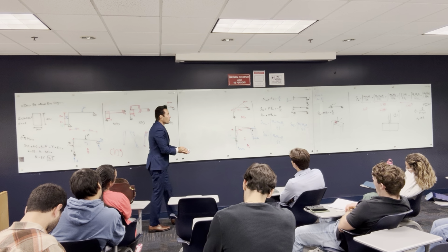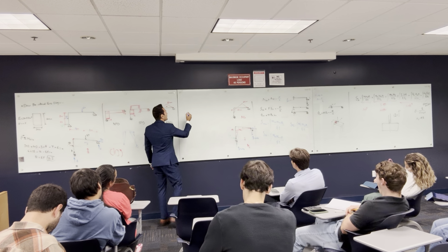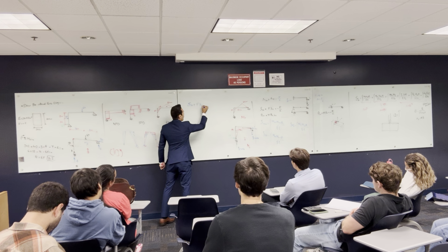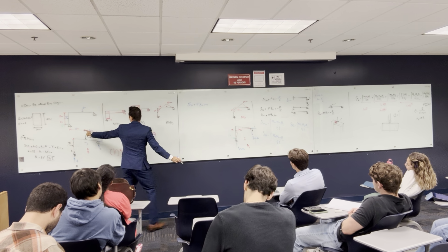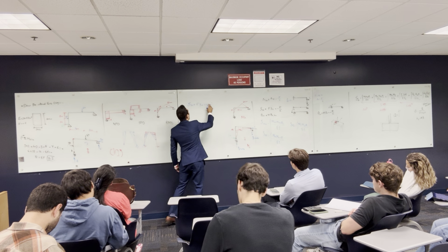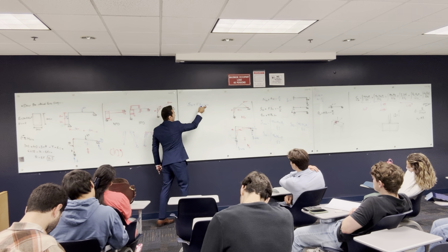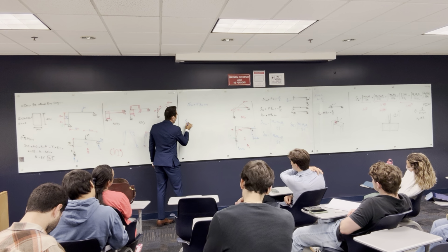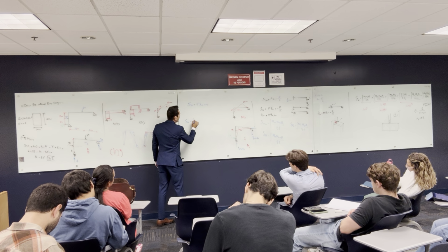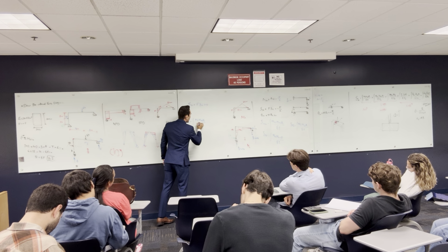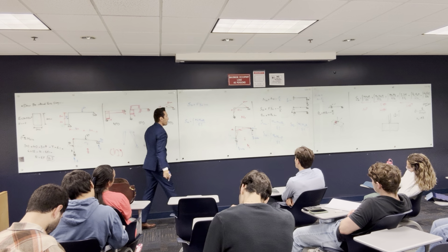So I want to solve the compatibility equation: delta 1O plus F delta 11 equal to 0, because I have a hinge here. There are no springs, so this is equal to 0. If I find delta 1O and delta 11, I solve the whole problem. So how can I do this? Delta 1O is going to be the integration of M1 M0 dL over EI.